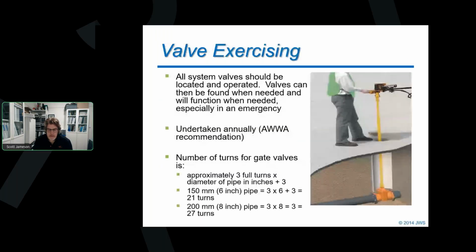Valve exercising is also very critical for this. Before we get out and actually do the plan, if we've identified that I'm going to close this valve here, I'm going to close this valve over on this street, I need to go out there and make sure that I can find that valve, make sure it exists. If it's buried, dig it up, and I need to exercise it, right?